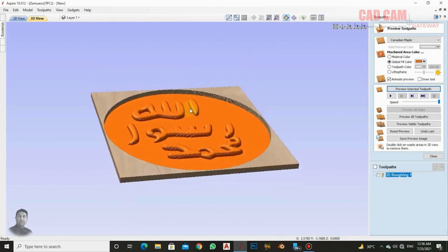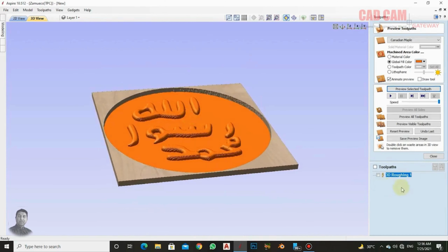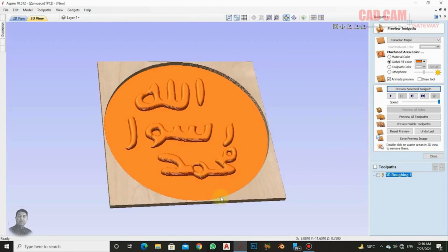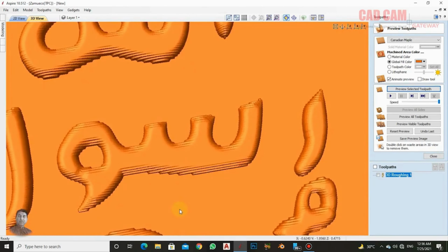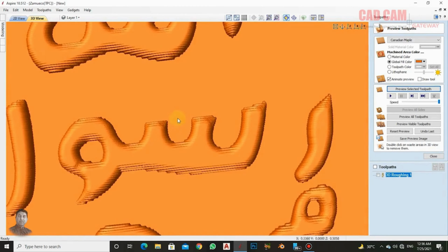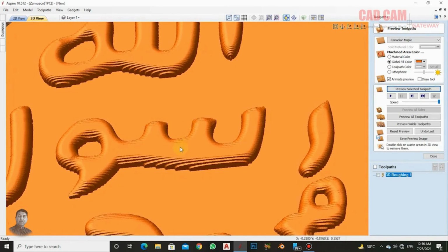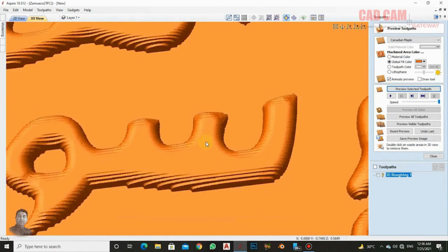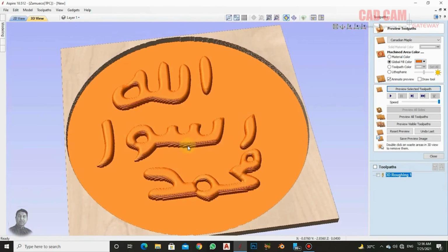See, it did it in 2 passes. Now, obviously, the depth is greater, which is why it took 2 passes, but still, you have the option to reduce the number of passes even further. Anyway, you must have practiced this by now, so you'll be able to work on it. Look, when I did the roughing with the end mill, you can see that the steps are quite large. Why? Because our cutter is a large size end mill cutter.